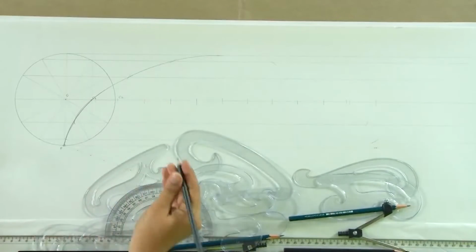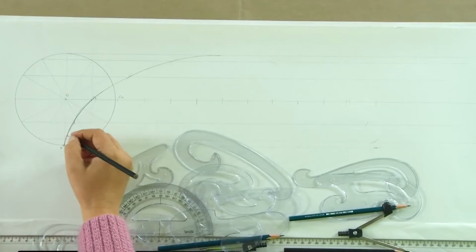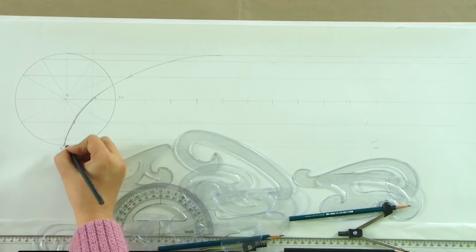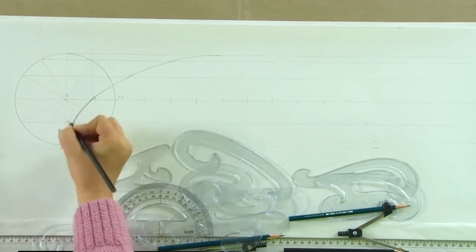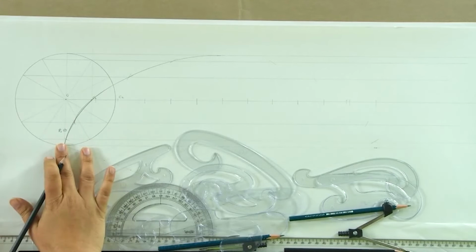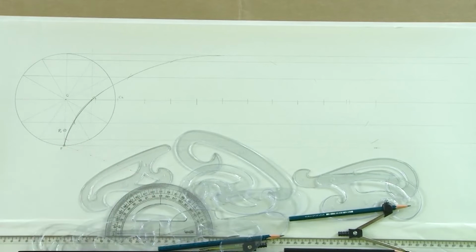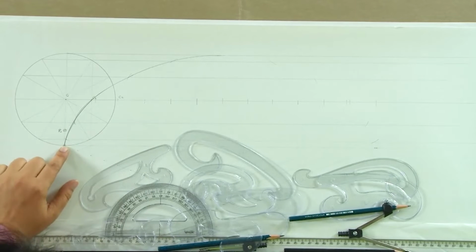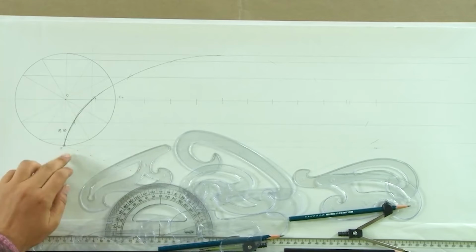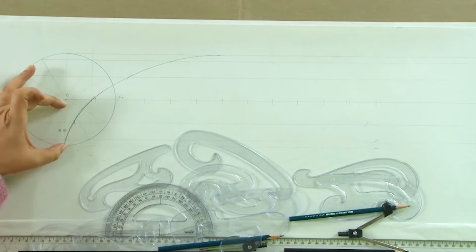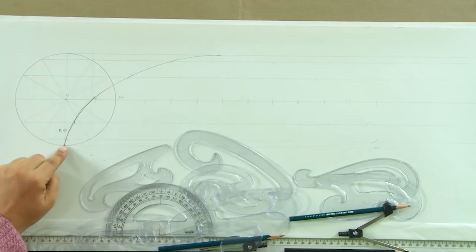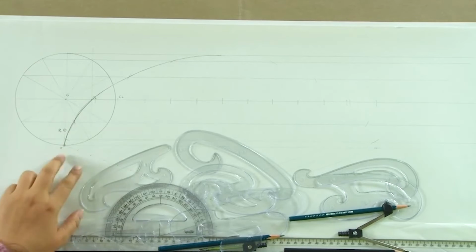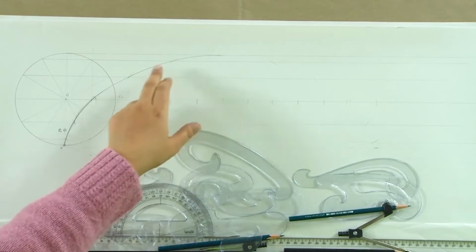So, if we were to draw a trochoid, the only thing we would do is, for example, we had a point which was not this, but there was a point P1 here. So, if we were to draw a trochoid, instead of this point and the distance CP, we would have taken the distance CP1 and we would mark the movements along these horizontal lines.